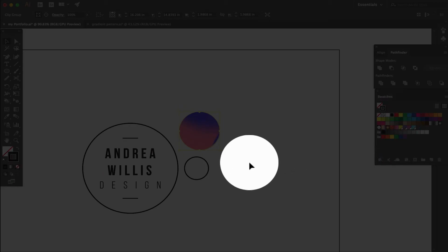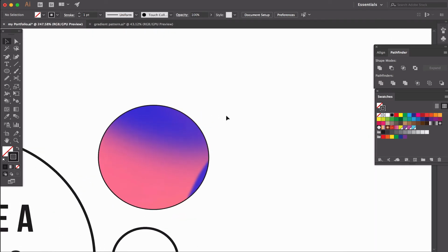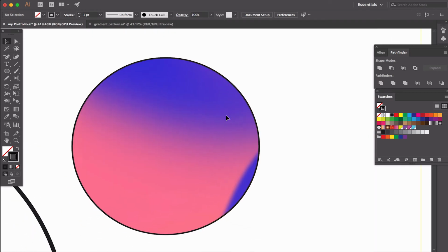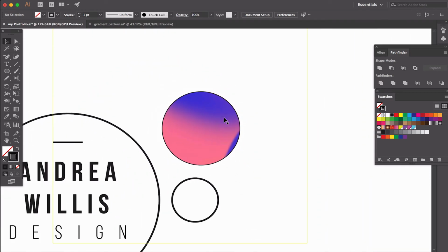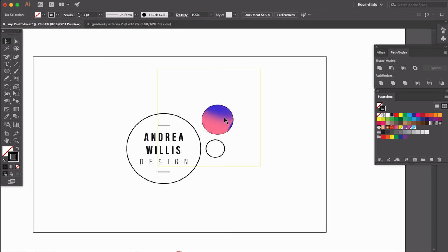If your pattern is not a vector and instead a JPEG or PNG, you'll want to make sure that it's a 300 dpi or print resolution file for the best results. You can include multiple treatments in your design, such as an engraved color fill with a cutout or an engraving with a UV print, by using the guidelines provided.